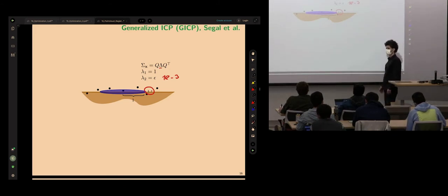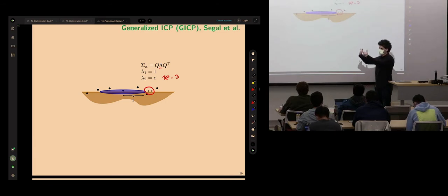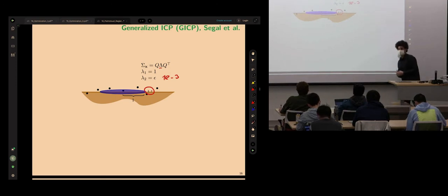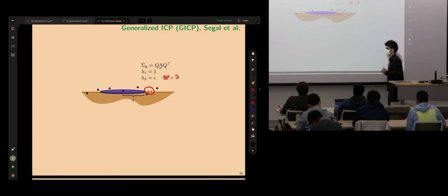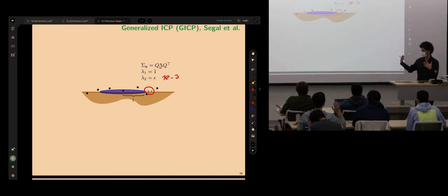This is a good idea, because when you have a wall, you don't want the measurements that are coming from that wall to move in the direction orthogonal to the wall. They should just slide within that plane that they're supposed to be. This assumption is reasonable if you assume the environment is like that. If you go to an unstructured environment, it's not clear it will do so much for you, and it won't. But on roads, for example, in the city, urban area, it's still a good assumption because of the buildings and road structures.